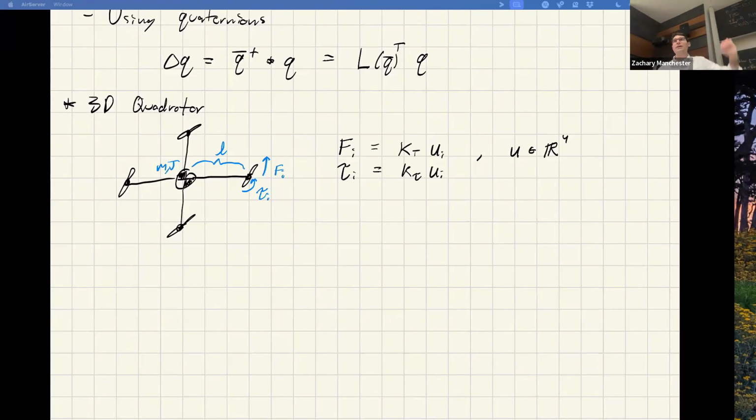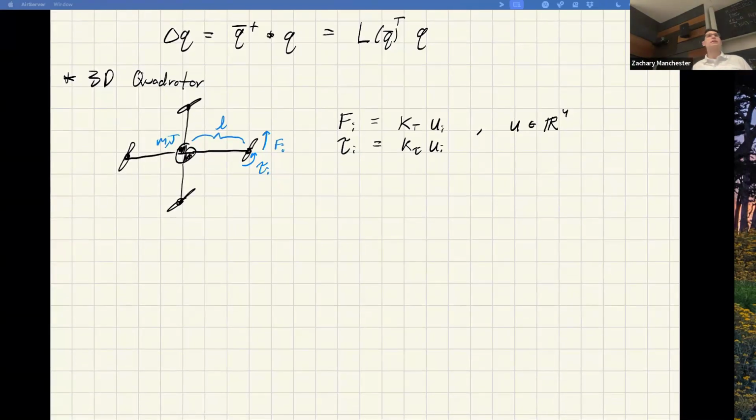So that model starts to break down. If you fly really fast, the ambient flow field dramatically affects what the prop does, and these linear coefficients start to break down. But near hover, this is the valid model. You just keep adding terms to this to make it better. Yeah, so basically what ends up happening is the standard thing for this kind of model is